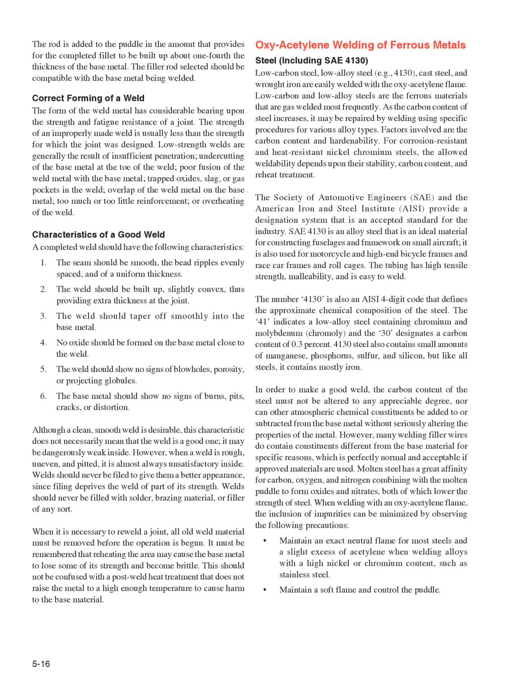Although a clean, smooth weld is desirable, this characteristic does not necessarily mean that the weld is a good one. It may be dangerously weak inside. However, when a weld is rough, uneven, and pitted, it is almost always unsatisfactory inside.